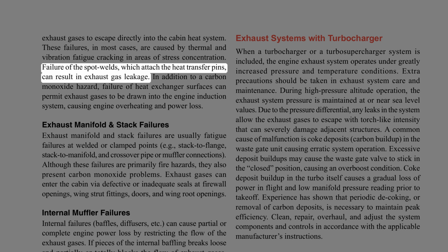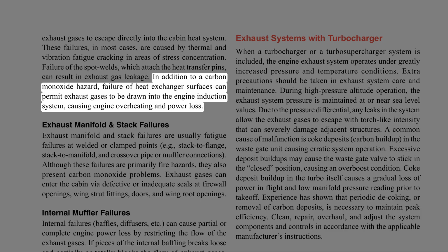Failure of the spot welds, which attach the heat transfer pins, can result in exhaust gas leakage. In addition to a carbon monoxide hazard, failure of heat exchanger surfaces can permit exhaust gases to be drawn into the engine induction system, causing engine overheating and power loss.